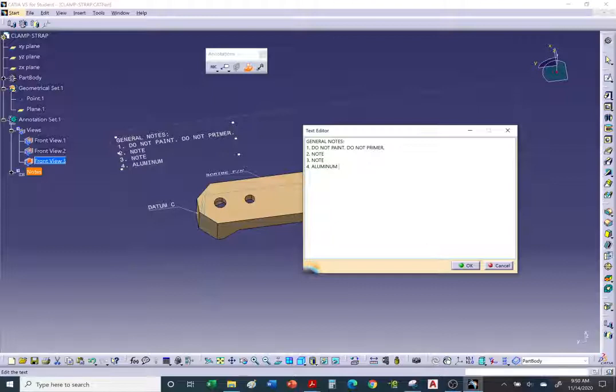And I'll say this time I'll use 7075, which is a very strong aluminum alloy. Typically in aerospace, when you're machining structural members, we go with the higher strength aluminum alloy, 7075. And the temper, I think T651 is a common one. The temper can be the aging of the material or the treatment of the outside of the material, how it's treated to be aged. Think of putting a Quizno sandwich in the oven, right? If you go order a Quizno sandwich and they run it through and they heat it up, it makes it stronger, right?